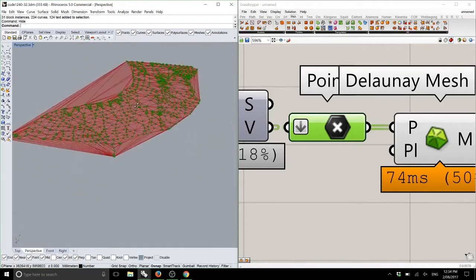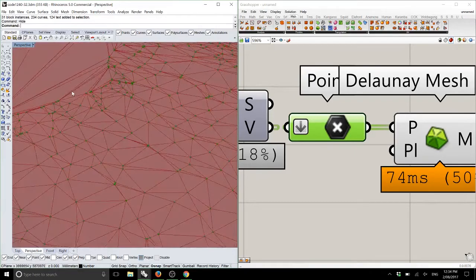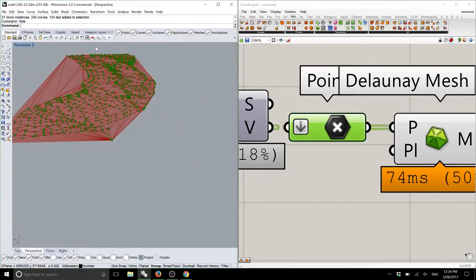So one way of doing it is, like for example, this is kind of a mess. We don't really need to know what's actually happening up there, so we could just go through and manually delete it. But a good way of doing it is actually taking the boundary of our site, offsetting it by a few tens of meters, depends on the scale, and then just trimming that. Cool? So that's what we're going to do.